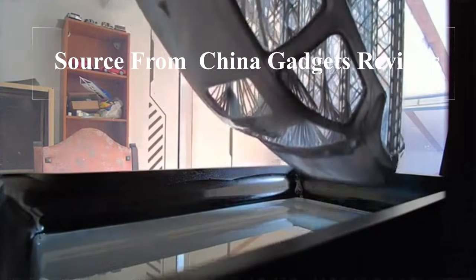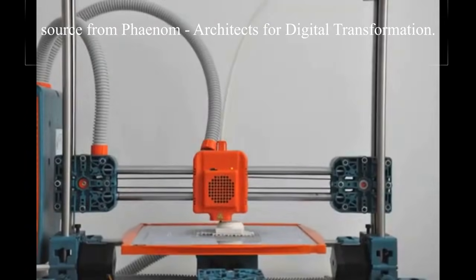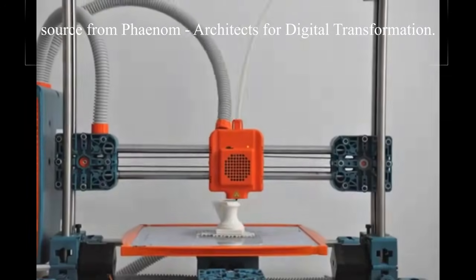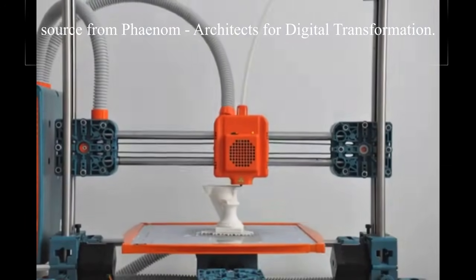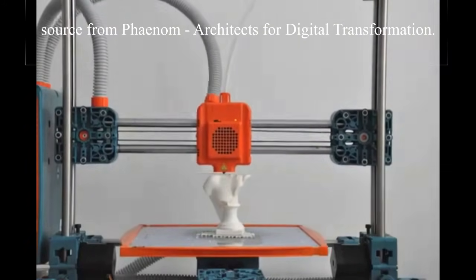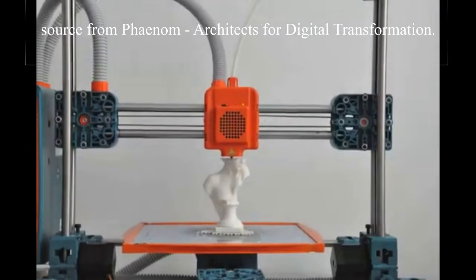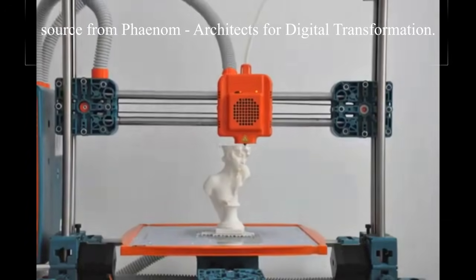This approach nets us a 2.5-degree operation, essentially a series of discrete 2D planes stacked along a single vector. In manufacturing, we call this 2.5D machining, because the tool is never truly free in 3D space while it's depositing material. This sort of arrangement is the most common approach to 3D printing in general, whether it be FDM, SLM, or SLA. There are several factors as to why this is the case. To name a few, it is incredibly simple to program, and it has very few moving parts.